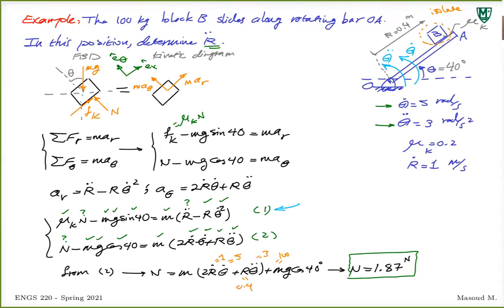All right. So again, the procedure is pretty straightforward, I think. Free body diagram, put the forces there, put the components. The only thing that changed compared to Cartesian coordinates and tangent-normal coordinates is that you're putting different acceleration components. In this new coordinate system, you have to remember what the components of acceleration are, just plug them in and apply Newton's second law. The rest is just decomposing vectors in the right directions and forming the two equations that you get.